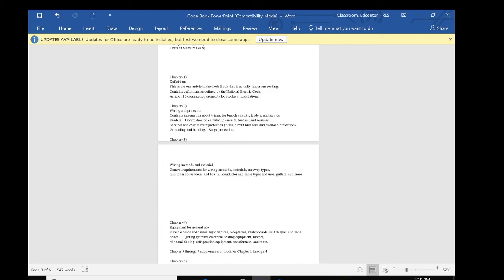It has a section in there, like you'll see NM cable, which is Romex, in Article 334. So for every specific type of these materials and cables, they have their own little section that tells you everything: what you can and can't do, how you have to install them, where you can use them, where you can't use them. So Chapter 3's got a lot of stuff in it.